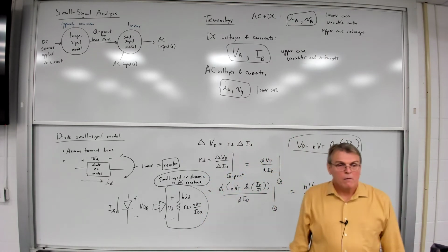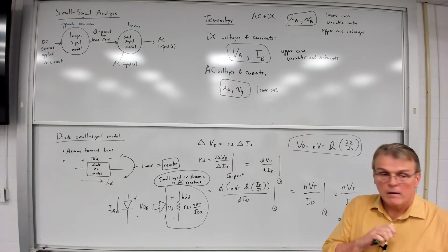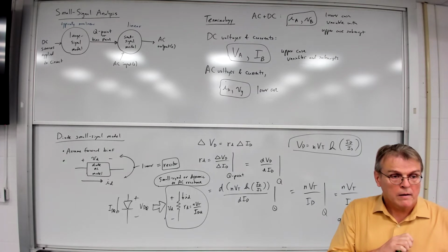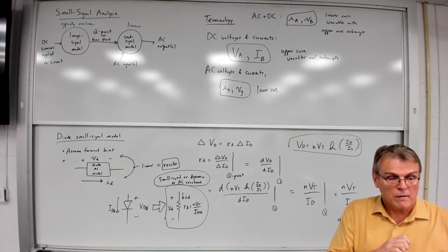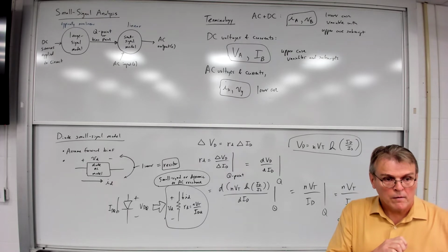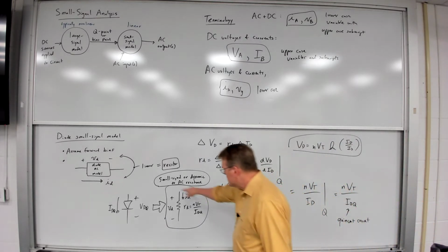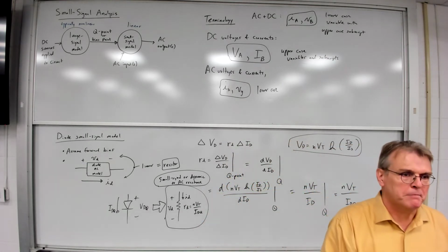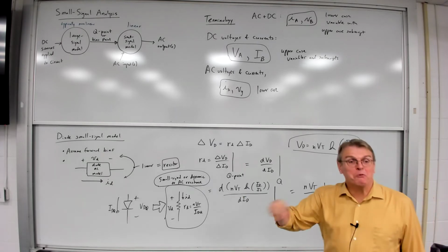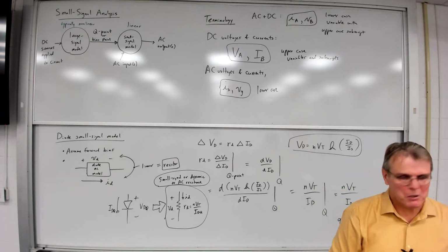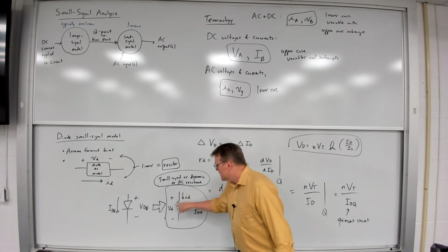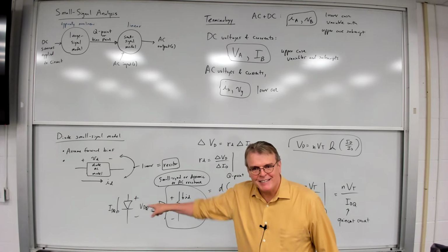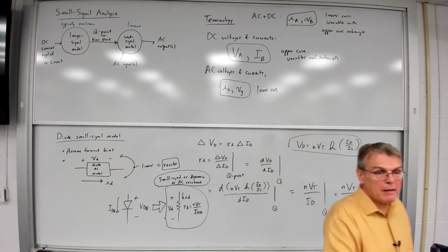Yeah? So we are basically assuming that after we transform it to a resistor, the small AC current and small AC voltage are not impacted. Well, the AC voltage and the AC current are going to be the result of an AC source that we apply to the diode, which we haven't shown yet. Once I go through and work the rest of the problem, this will become clear to you. For now, these small signal AC voltages and currents are not the result of the bias. They are a result of AC sources being applied to the model.